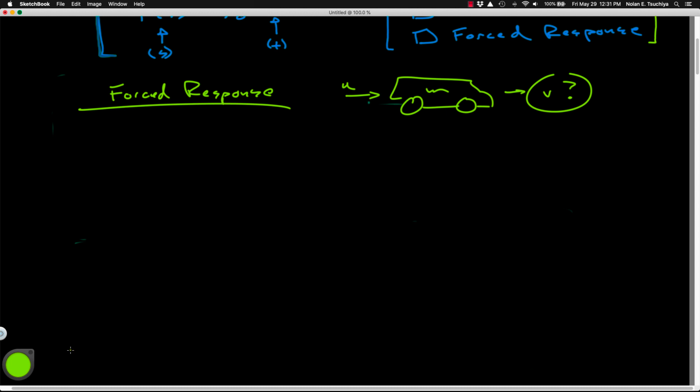Okay, for this system, we've already modeled the vehicle velocity dynamics, so let's just use that. Starting from where we left off of last lecture, we had that v dot is minus b over m v plus 1 over m u. So basically it's v dot equals minus a constant v plus some other constant times u. So we can plug in some actual values. Let's just keep this example simple. Let's just say it's minus 10v plus 2u. Okay, so we just plugged in some values for b and m, and now we've got this differential equation that is driving the dynamics of that system.